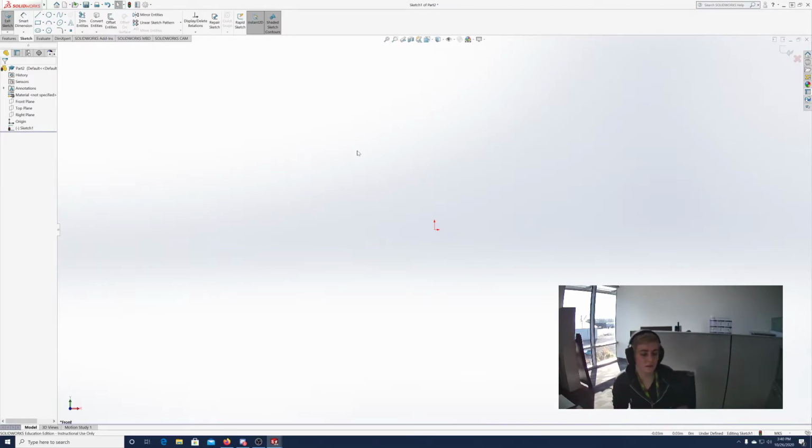If it's showing something else, that's probably happening because you've got some other point selected. So it's giving you the distance from the center of that circle to another point. It's probably because you clicked the other point first and you didn't get out of that. So just hit escape or click somewhere else to let go of that other point. Does that make sense?